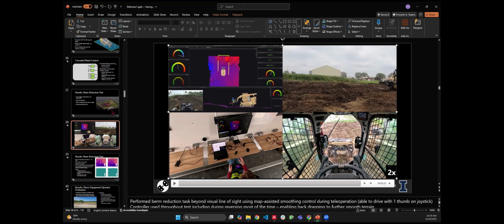But that one was running a real-time patched kernel. I think it was a server version of Ubuntu 22.04. And then the other computer, the control computer, was also running a real-time patched version. We did some initial tests with and without the real-time patching, and I think we got more consistent latency performance, in terms of threading and that kind of stuff at the kernel level.